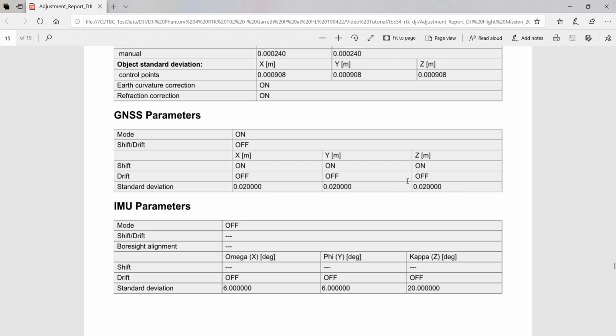So you cannot start when we don't have high accuracy positions for our images, and if we did not measure ground control points. But in our case, no ground control point was measured, and everything is based on the high precision of our drone imagery. Okay, so far for this video.